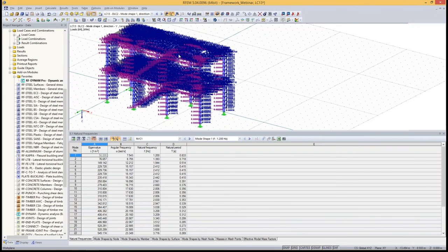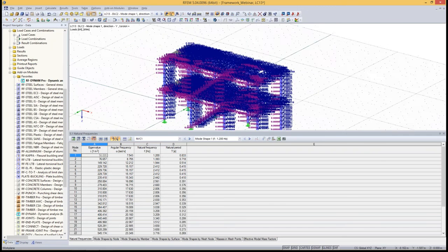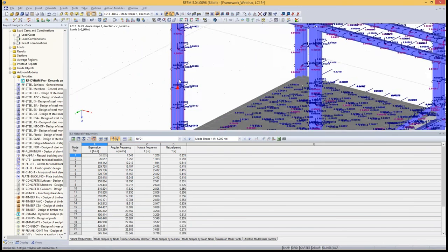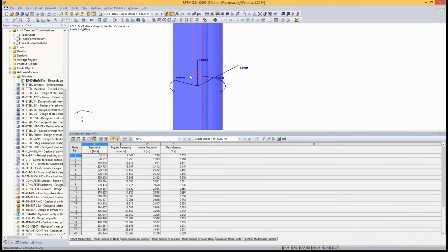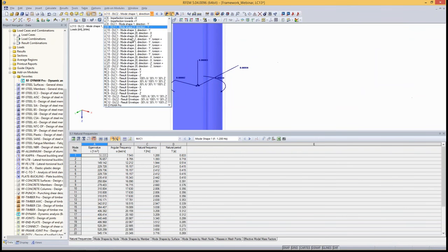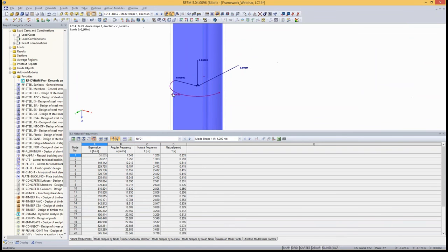Let's just have a look at it. It looks terrible if you don't zoom in. You have so many loads, but if you zoom in, you see the applied equivalent loads in all 3 directions, and you see the torsional moment. This is the torsion plus case. And if I switch to the other case, the only thing that changes is the direction of the torsional moment. The number stays the same and the equivalent loads stay the same as well.